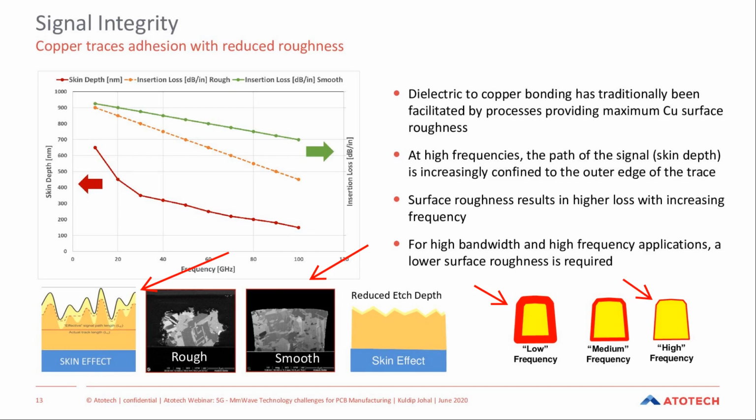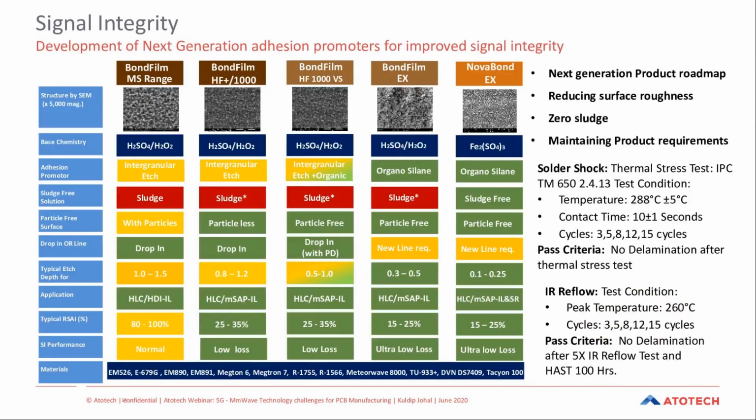And what we can really say is if we improve our surface roughness, we can improve signal integrity. And typically that improvement can be 5 to 8%. But talking to signal integrity engineers, that's still a gain that they want to see.